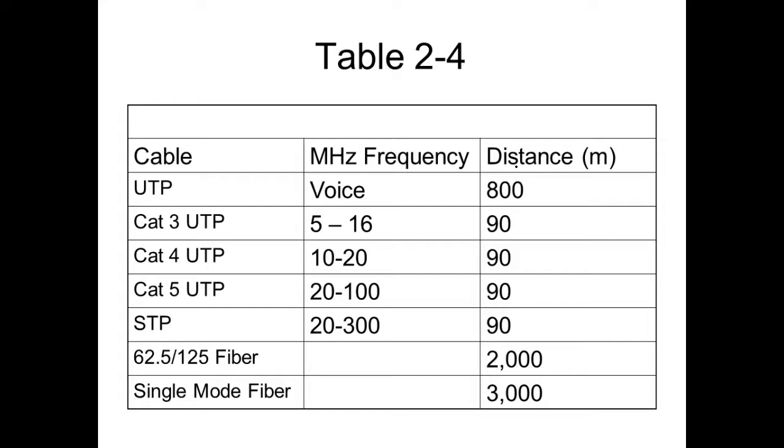Because it's networking, we're using 24 gauge wire. It's copper, 24 gauge copper wire, but it's still 24 gauge wire. So it's pretty thin wire. Of course, we do that to make the size of the wire small so we can route it a lot better. So yeah, this is 8 wires. It's a 4-pair wire, so it's 4 twisted pairs in here. And that cable's pretty small, right? So we can route this to a lot of different places. And it's also thin, even though it's solid strand. The strands are so thin, it still makes it fairly flexible, even though you're not supposed to.